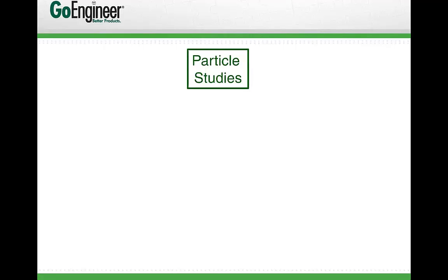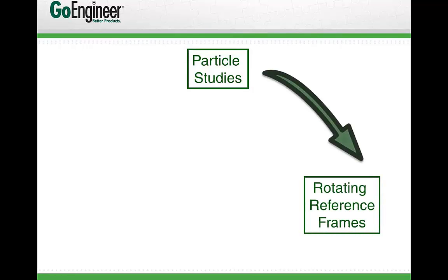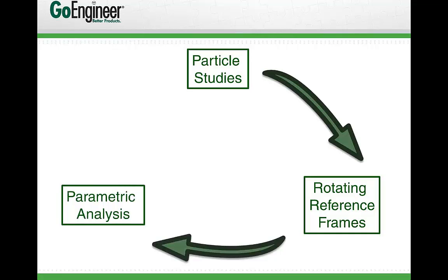The first thing we're going to take a look at is something called a particle study. We'll get into this pretty deep, and you'll see the power of this, where we can include real particles and their behavior. Then we're going to take a look at rotating reference frames, a technique used to analyze things like fan blades, impellers and parts that are rotating in usage. And then we're going to go on to a parametric analysis, which is an optimization study, based on shape optimization of the geometry.